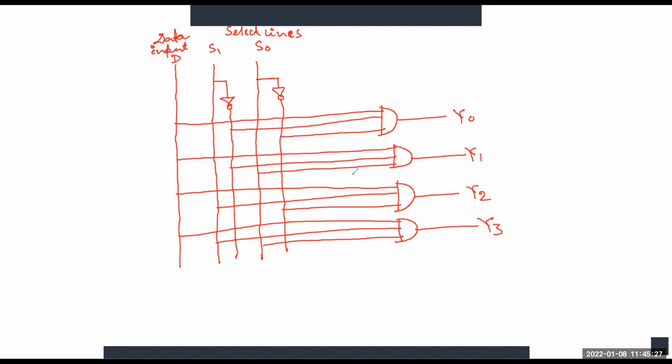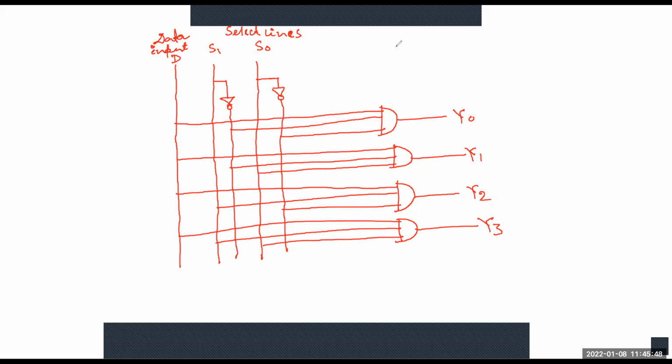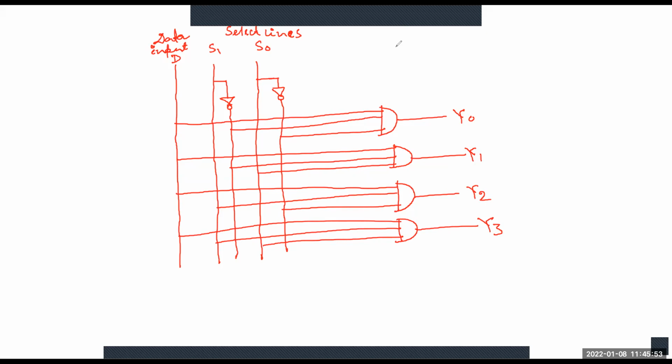You also know that whenever there is a multiplication expression, multiplication means we need the AND gate. So here we are using the AND gates. To implement the 1:4 DEMUX, we need two NOT gates and 3-input AND gates. With these gates we can easily implement the 1:4 DEMUX.